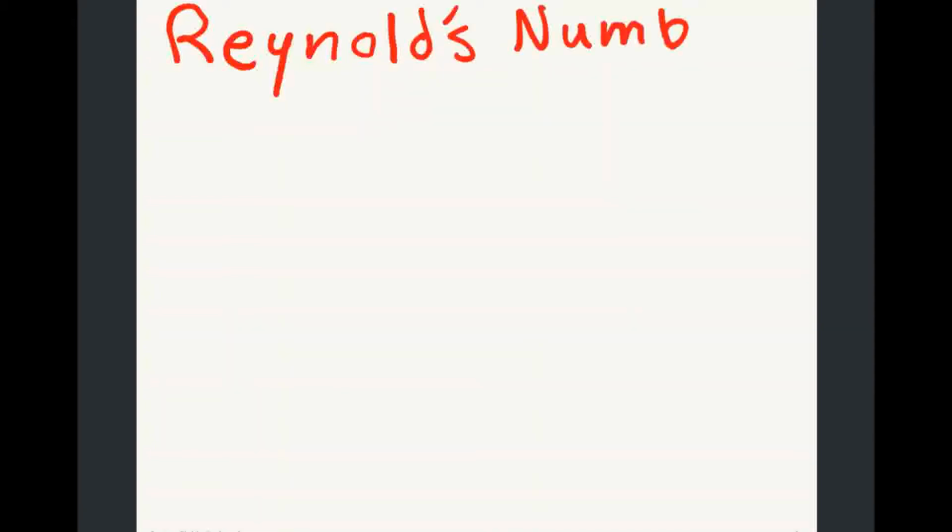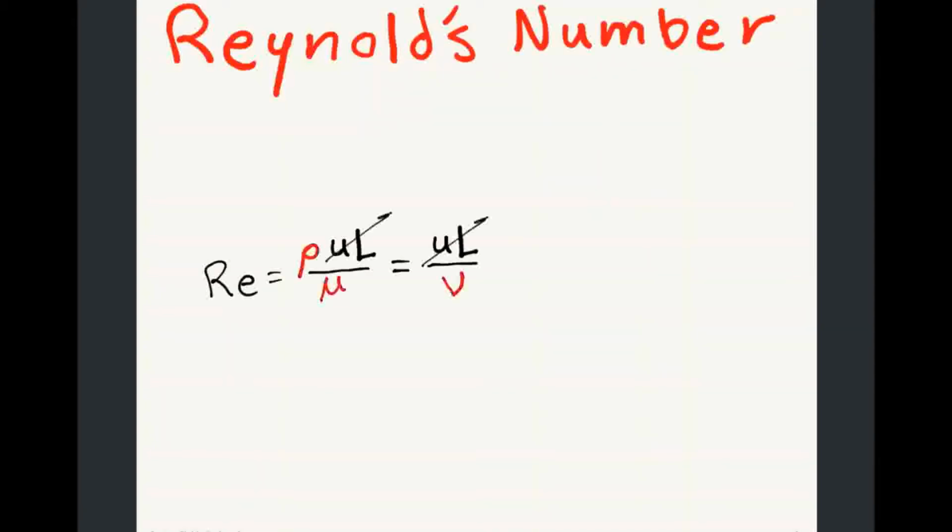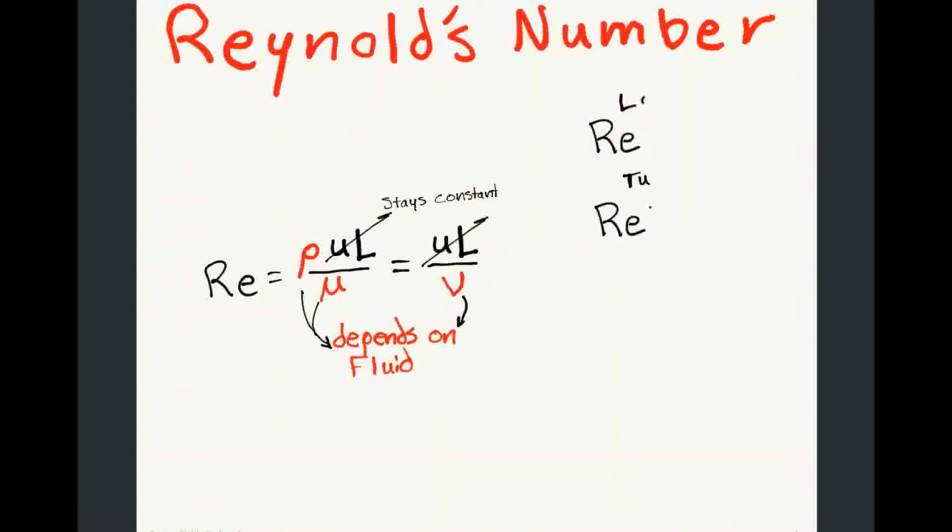The Reynolds number is a ratio of the inertial and viscous forces, or the ratio of destabilizing to stabilizing forces. Thus, Reynolds number describes the quality of the flow. Greater destabilization in the net forces results in turbulence. Contrastingly, laminar flow systems have very predictable fluid movement. So predictable, in fact, that we can reverse the mixing that happens utilizing laminar flow.